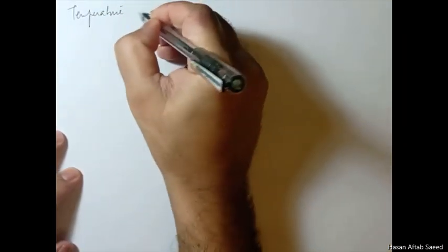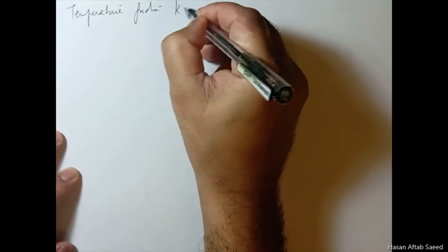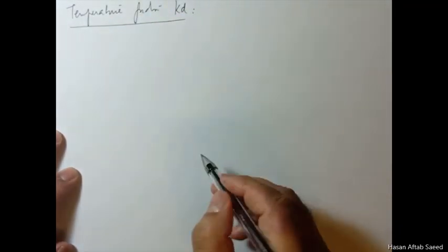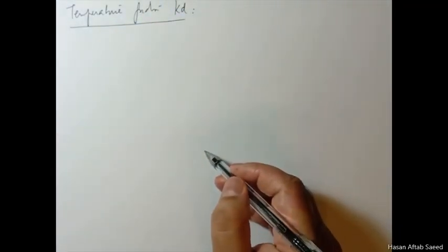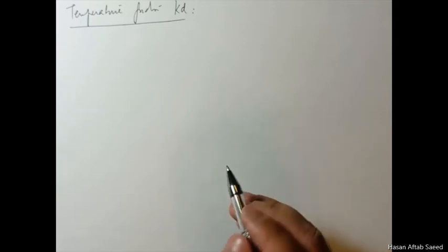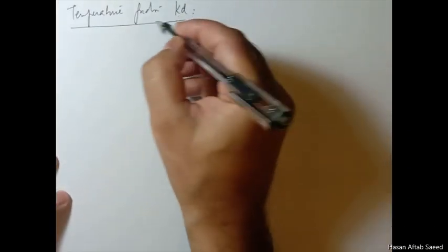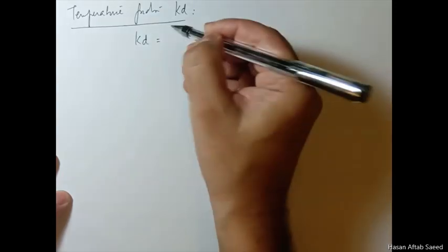Now we come to the next of our factors, the temperature factor Kd. For steels, when we increase the temperature, initially up to about 150 centigrade, there's a slight increase in the tensile strength, and after that there's a drop, and sometimes it's a big drop. Now this ratio is the correction factor.